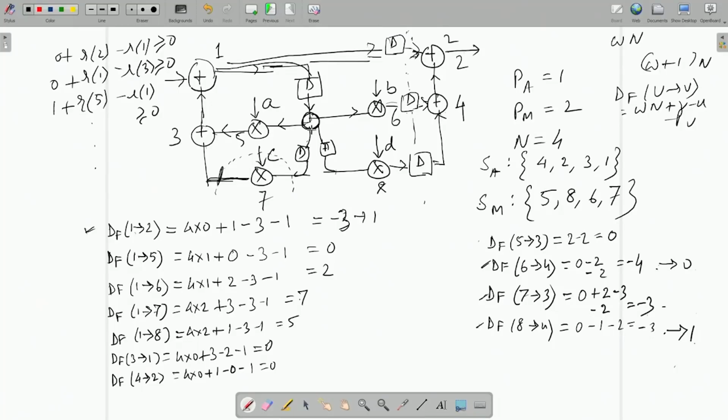Now, see what edges I am cutting. I am cutting this edge and this edge. So, they form a valid cut set, because if I remove this, this node is a singleton left out and the remaining part of the circuit is another part. So, the entire DFG or circuit is cut into exactly 2 mutually separate DFGs. One is the single node 7, the other is the remaining part of the DFG. But one is incoming direction, that is, the edge is coming from the other half of the DFG to node 7, and another is going out of node 7 to the other part of the DFG. In one incoming edge there is a delay, this I can cut, so I can bring back the delay on this side. In one direction I remove and add the same delay in the other direction, that is the formula.